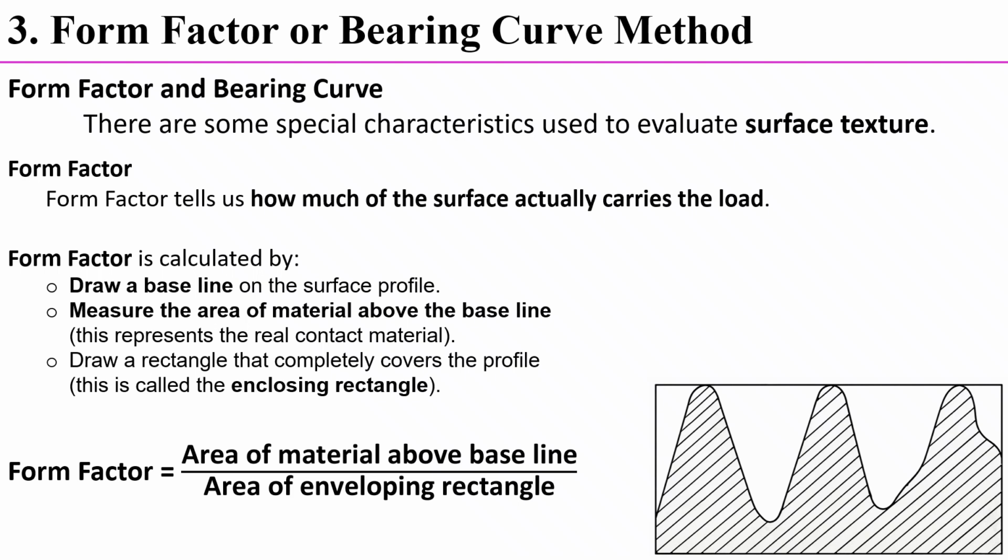Next we will discuss the form factor or bearing curve method. So form factor and bearing curve methods use some special characteristics to evaluate the surface texture. Form factor tells us how much of the surface actually carries the load. So let's see how to calculate this form factor. First we have to draw a baseline of the surface profile. So this is the baseline for this surface profile.